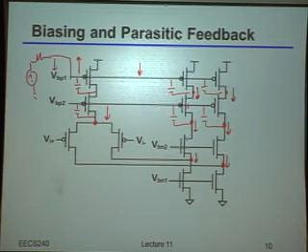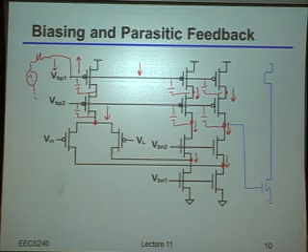Okay? So let's just say that I actually needed more gain than I got from this one structure here. Okay, let's say I actually needed another gain stage. All right, and let me maybe draw this in a different color here. Okay, so let me do it like this. So I'm going to build that extra gain stage. Just as an example, I'll build another, let's say, common source amplifier. Okay? And just again, because, hey, why not? I'll bias that current source for the common source amplifier using the same bias once again. Okay?